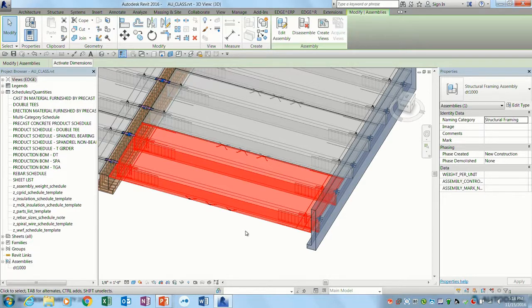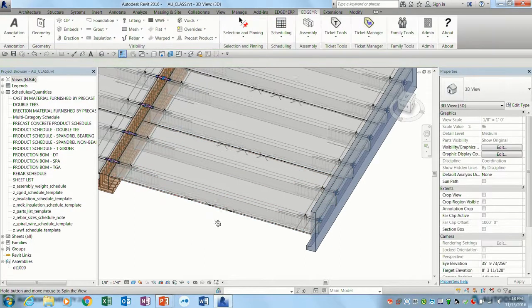So they've provided a tool that's called the Assembly Origin tool. It's a set of axes that you orient. And what that does is it allows you to set up the box. So you imagine a conceptual box around this thing that you want to detail or document. However we orient that assembly is going to orient that box. So we could orient it skewed, orthogonal to this member. Our standard, of course, and I assume most everyone's standard, is to orient it orthogonally.